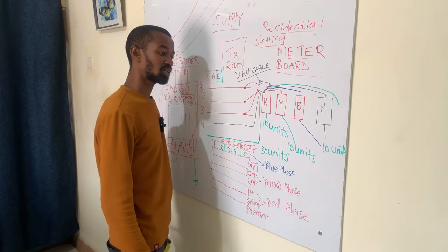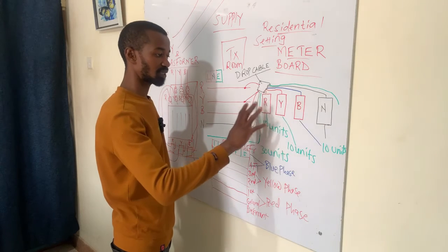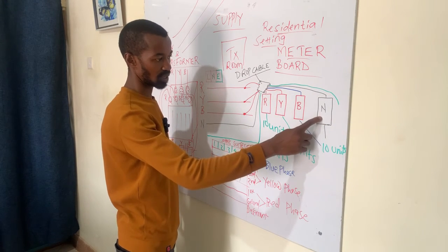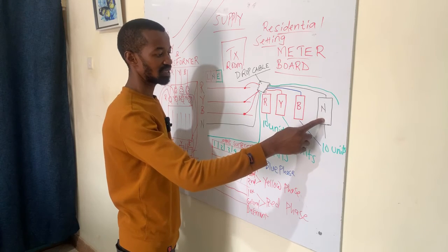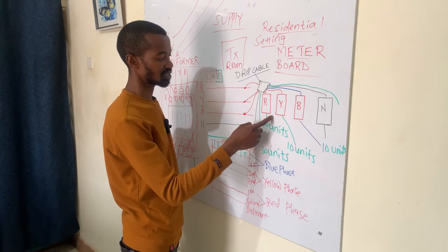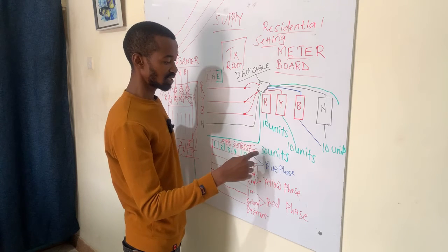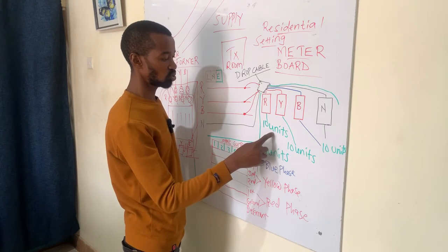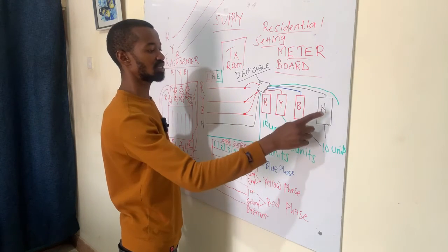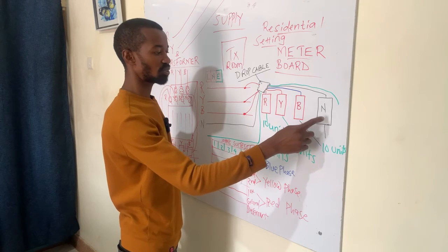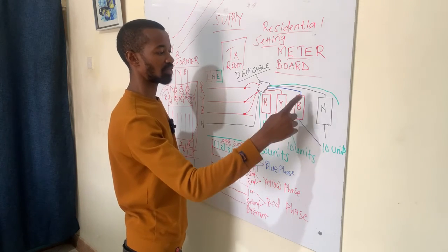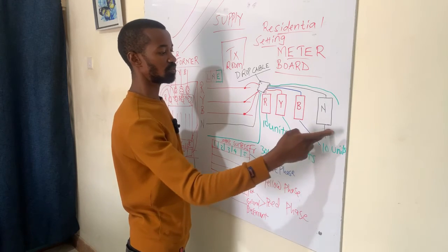Now, as an electrical technician, when you are doing this type of setup, you must be very careful with this cutout here. Why? This cutout is a return path for all the 30 units. The phases are each supplying electricity to only 10 units, and these phases rely on this neutral connection, or this neutral cutout, as a return path. So all of these will be returned here.